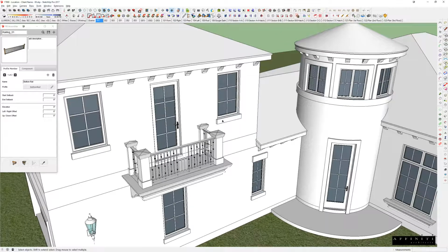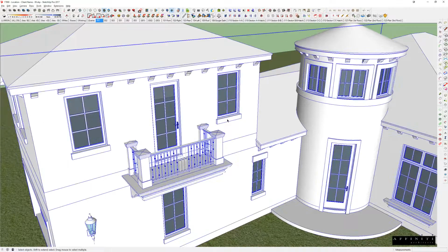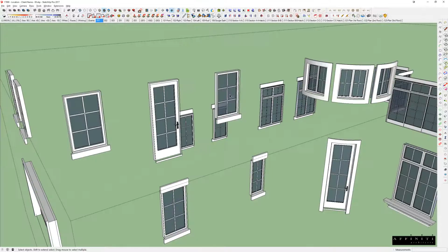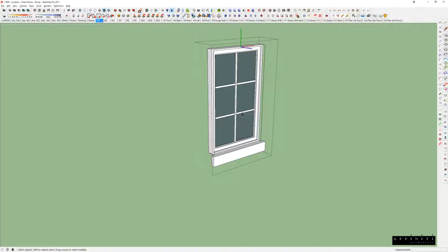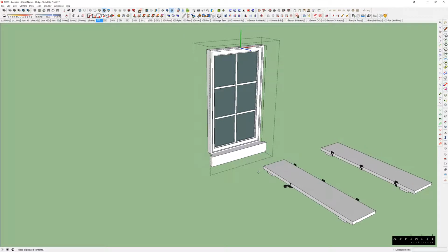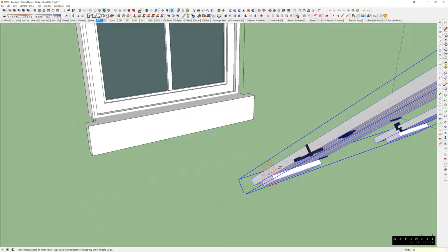And before I paste it, just like before when we talked about the trims, you could either put the trim outside of the window block or inside of the window block, and it all depends on your model and on how many times that window is replicated, and if that same window throughout your house will get the same shutter or not. And so that's just going to be more of a call by you. It's definitely nice to be able to put it on inside of the window, because then you're just doing it once.